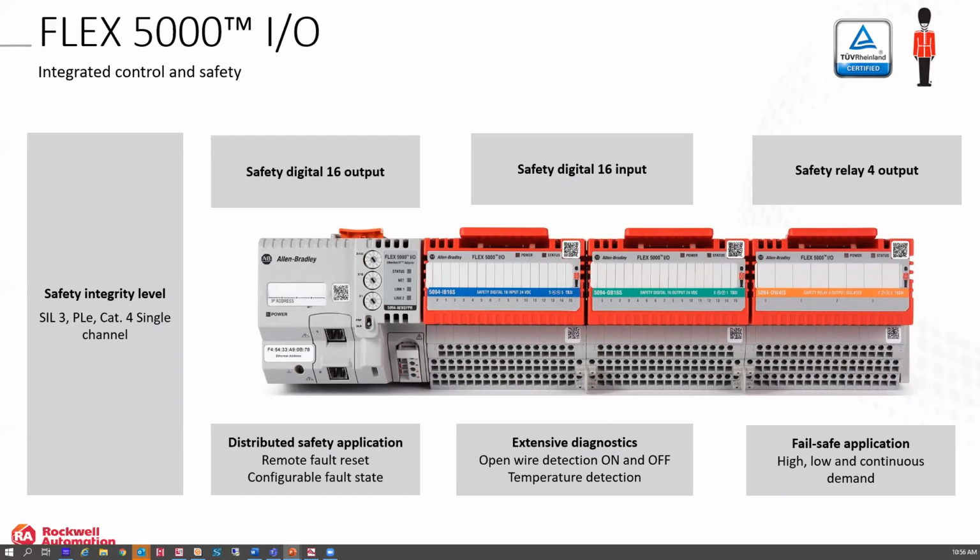Again, we can take this up to a SIL 3 machine safety shutdown type system. It's not fault tolerant IO. Again, this is for a shutdown type system, but we do have those modules available. And the nice thing about this platform is we can mix and match safety and non-safety IO in this application.